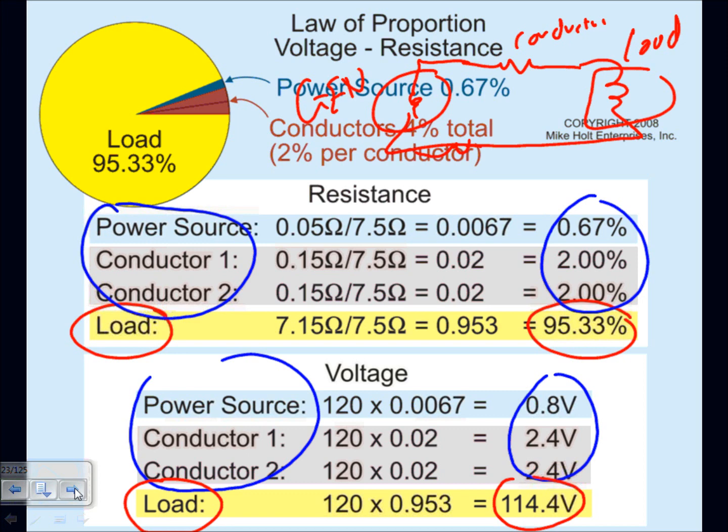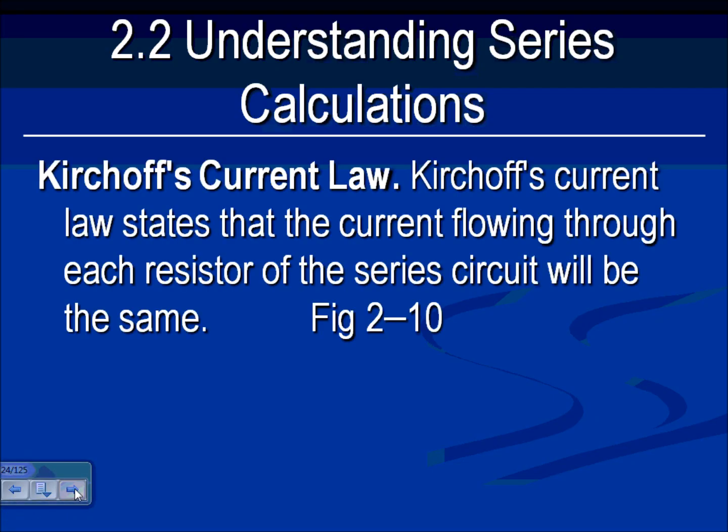Done with it. The voltage comes to us at 480. When I reach this panel right here, I better get as close to 480 as practical, within plus or minus 5%. You don't want to reach here and go from 480 down to 240 just by impedance of the conductor. So, okay, enough about that.